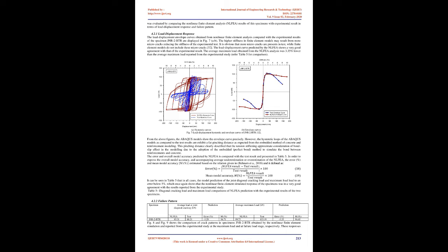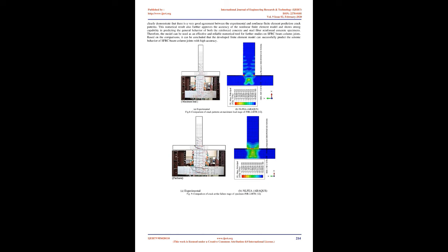Equation 14. Where is the fiber orientation factor in the three-dimensional, 3D, case? Hannant [41] used the value of 0.50, Soroushian and Lee [42] took 0.405, and Lok and Xiao [36] took 0.50 for slabs and 0.405 for beams. In the present work, is taken as 0.50. The value of the modulus of elasticity of steel fiber, 200 GPa, was used in this study as recommended by Amin and Gilbert [43].